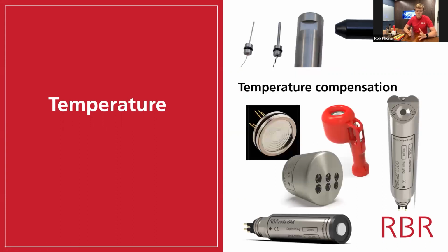So in addition to the regular thermistors, most other parameters or sensors that RBR manufactures use temperature for some form of compensation. And in fact, all of the sensors I'll talk about today use a thermistor in some form or another to compensate its reading.